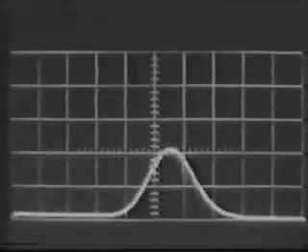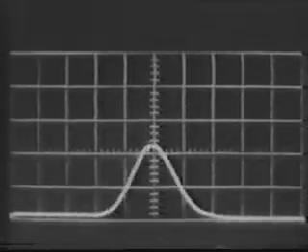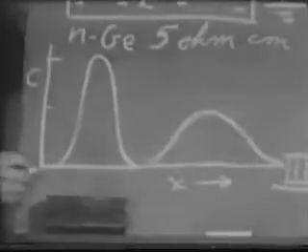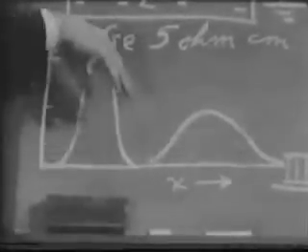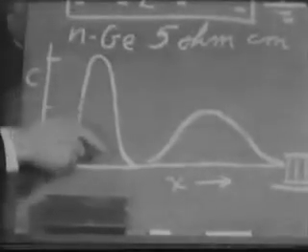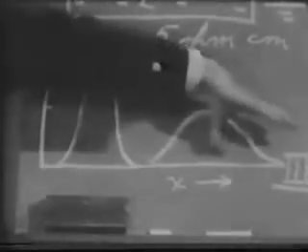You have noticed that as the delay time increases, the pulse becomes shorter and fatter. To understand this, we consider hole concentration as a function of distance. When the holes start out bunched together in a narrow pulse, there are big concentration gradients, and diffusion spreads them out rapidly as they drift down the bar.